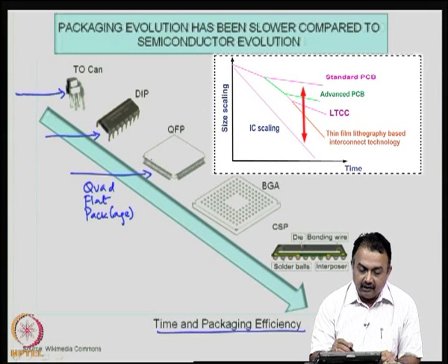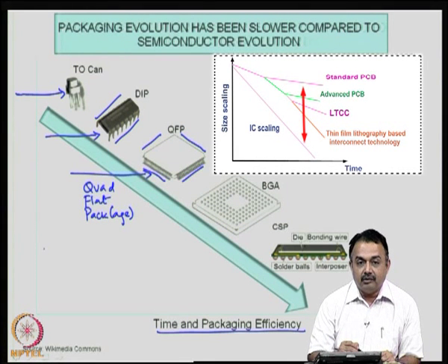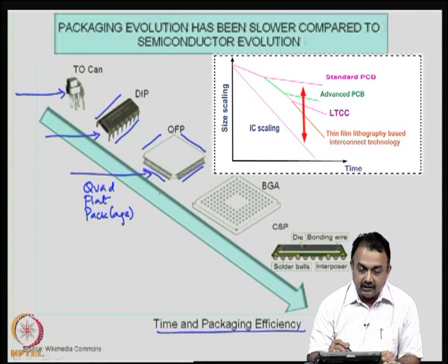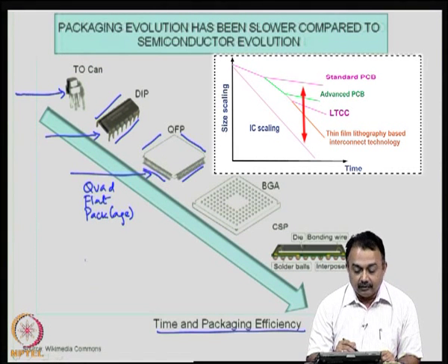Now, you can see from the name dual inline, there are 2 rows where the lead frames are. So, it is called a dual inline. Quad flat pack: the 4 sides, the pins are arranged symmetrically and the IOs are distanced carefully by a well defined pitch between the lead frames, and this is known as a quad flat pack. This also has got a package housing.